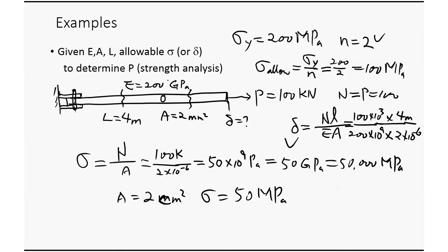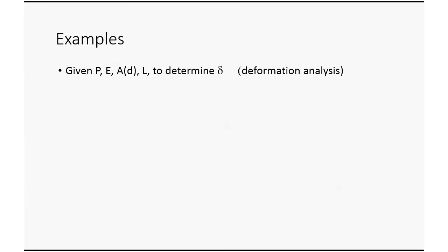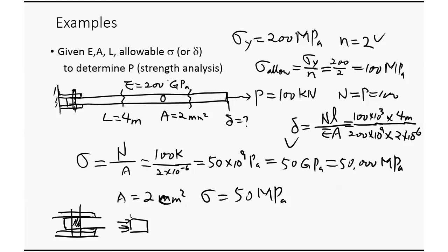You want to make sure the boat is safe, right? So let's look at the boat. Let's draw the boat bigger so you can see. The boat is here. So you have these 2 parts pulling on the boat. Now if I draw this part of the boat as a free body diagram, what is this boat under? Here it's under compression from the bar. And here it's under shear from the 2 sides, right?